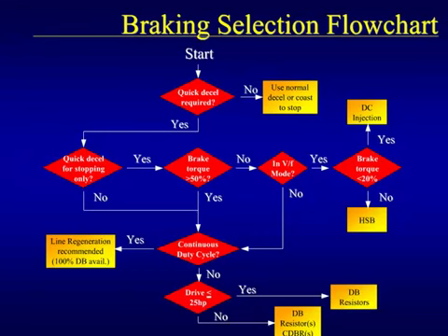Here is a flowchart that can be used as an aid when determining the appropriate type of braking method to use. This is a general recommendation, and actual braking solutions depend on issues such as size constraints, complexity of the solution, acceptable heating, power quality, and cost. The appropriate braking solution is shown in yellow. Note that there are two dynamic braking solutions shown in the bottom right-hand corner of the slide. If the drive is less than or equal to 25 horsepower, only dynamic braking resistors are required, which help to lower the cost. If the drive is over 25 horsepower, both resistors and transistor units are required.